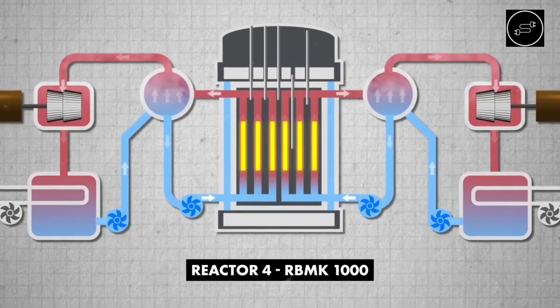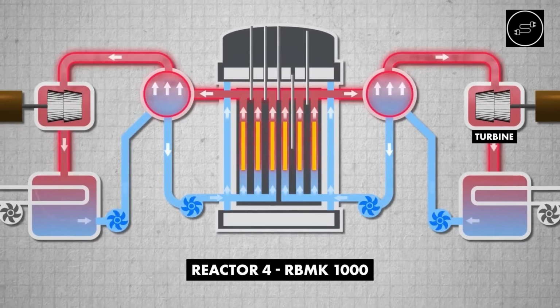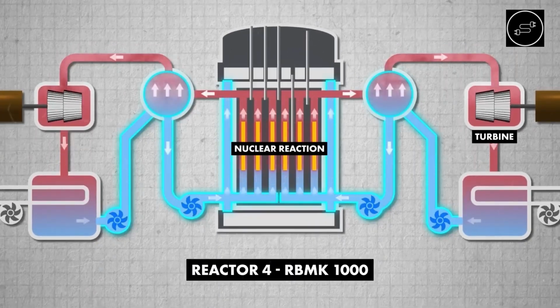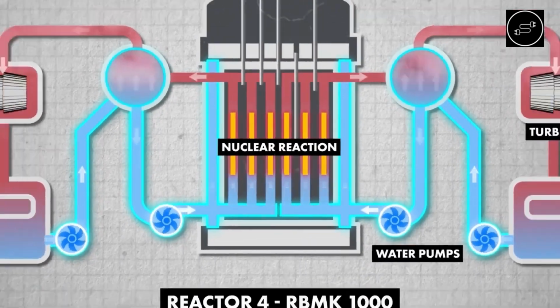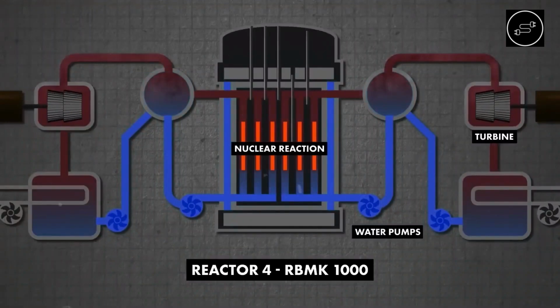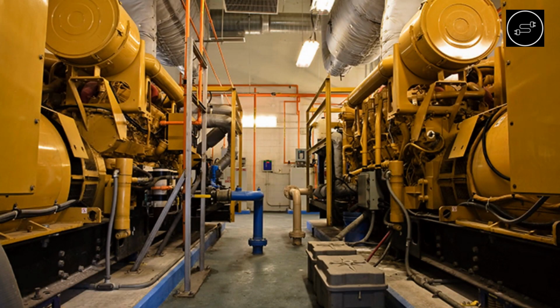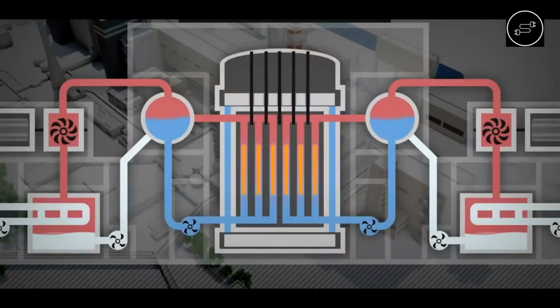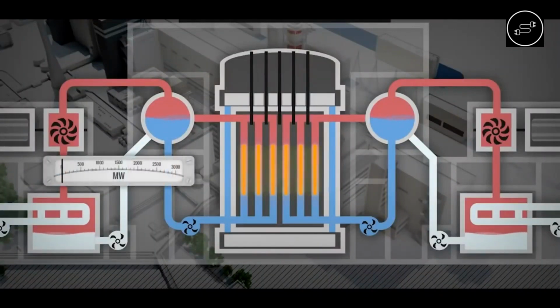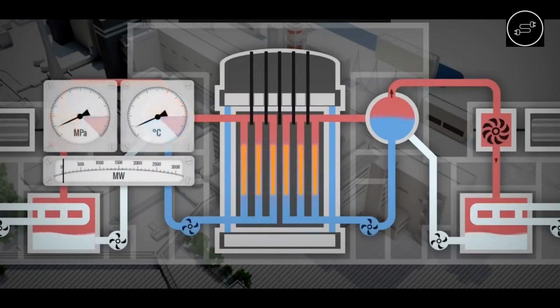Each reactor unit had 8 pumps circulating coolant water to absorb the immense heat. However, in the event of a power cut, these pumps needed continuous operation. Each unit was equipped with 3 diesel generators to restore power, but these required 60 to 75 seconds to reach full load. To bridge this gap, engineers relied on residual turbine momentum to temporarily power the pumps. Unfortunately, this system had critical flaws.